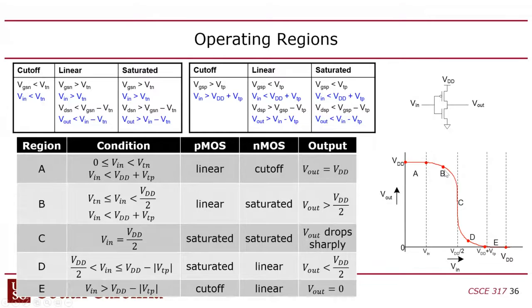And so basically, that's the thing you don't want to happen, right? You don't want them both on, because that's essentially what's happening. Not only are both transistors on, but they're in saturation mode, which means you're getting the most current you'll ever have flowing from VDD to ground. This is dynamic leakage current.